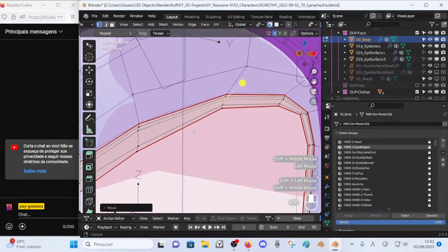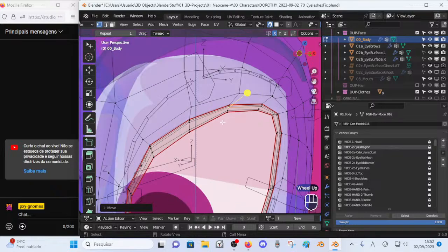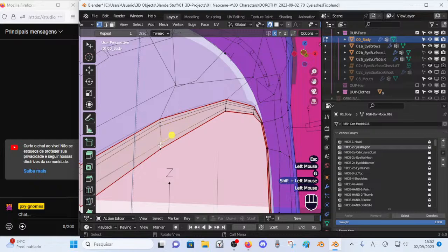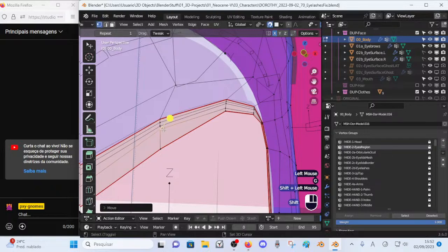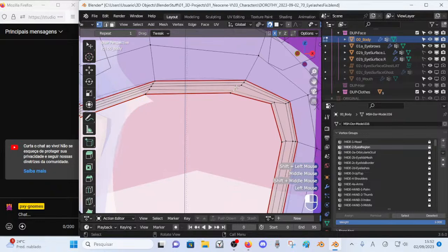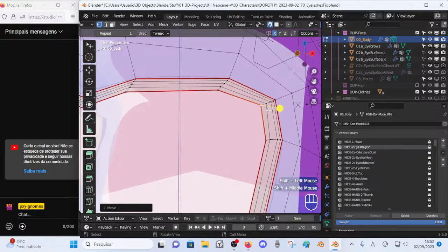And this looks good, because what I'm doing here, I'm changing the rest position just very slightly, so that as the eyes open we'll have approximately this kind of rest pose, right? This kind of rest position where the eyelids mesh is already mostly collapsed like you see here. Otherwise I'll have to create this system mechanically with bone constraints and or shape keys, and this can be really more difficult.